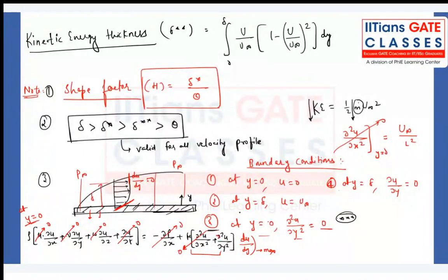For the flow over the flat plate, pressure will always be P infinity. Because for the flow over the flat plate, dou P by dou y will be 0. When dou P by dou y is 0, whatever the P is outside the boundary layer, that same P will be there inside the boundary layer. Understanding what I'm saying? Suppose there is a flat plate. Whatever the P is here, that will be the same as P infinity.